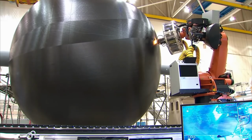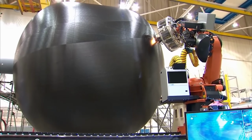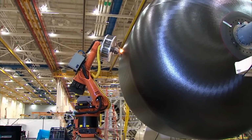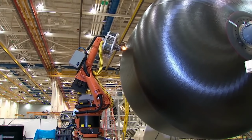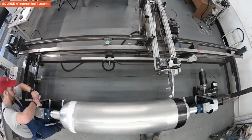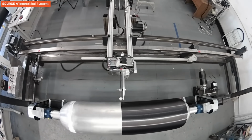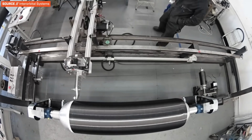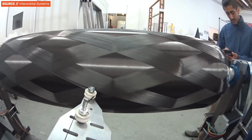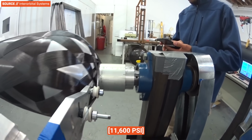So great lengths go into making tanks hold as high of pressure as possible while being as lightweight as they can. A common method for making lightweight, high-pressure tanks is by using COPVs, or composite overwrapped pressure vessels. COPVs are metal tanks wrapped really tightly with composites, such as carbon fiber or Kevlar, in order to basically keep them from bursting under extremely high pressures. COPVs typically operate at pressures around 300 or 400 bar, but some can get up to around 800 bar even.